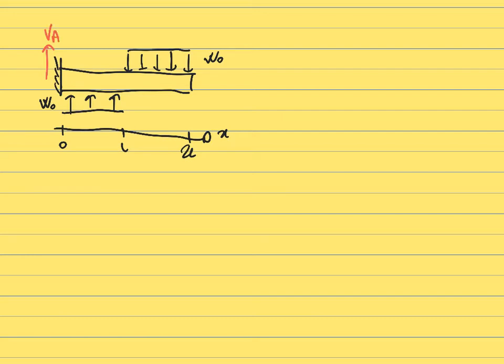So you have a vertical force that I will here decide to draw as going up. You also have a normal force. This one will also turn out to be 0, but nevertheless, it's a fixed support. So there's three unknowns. And then you have a moment. The fixed support prevents the rotation of the beam, so it's creating a resistant moment, which prevents the beam from rotating about this point A here.